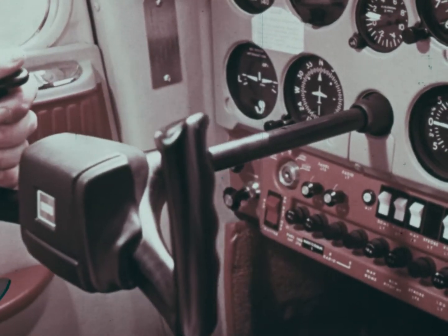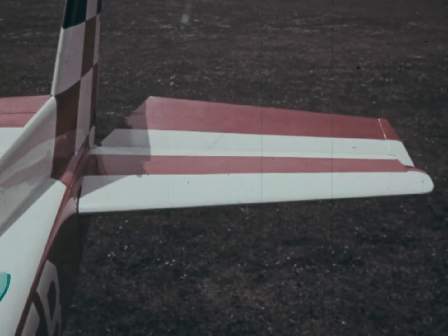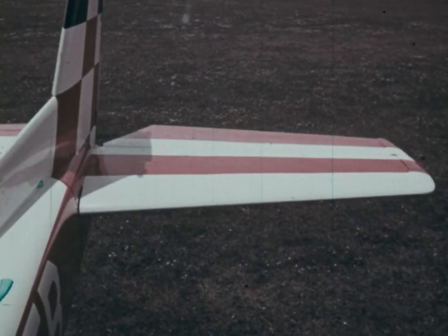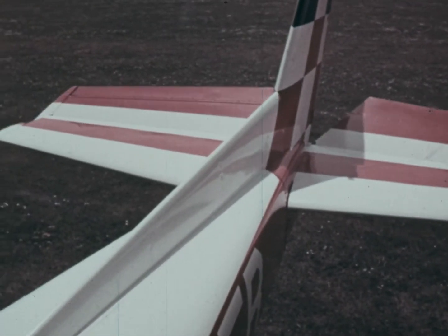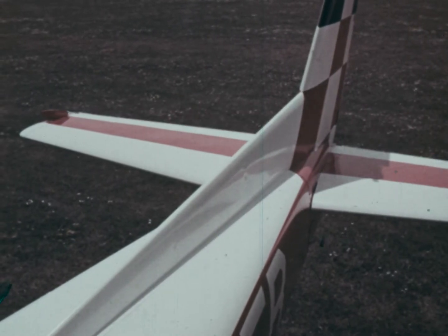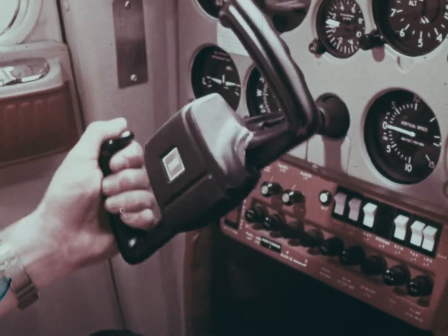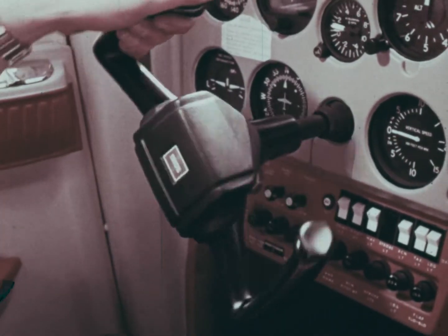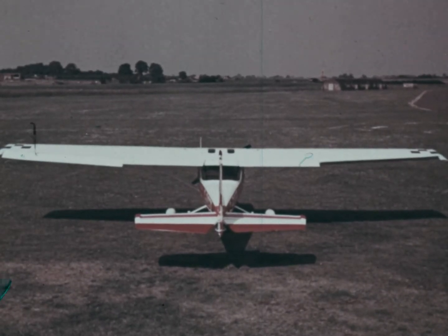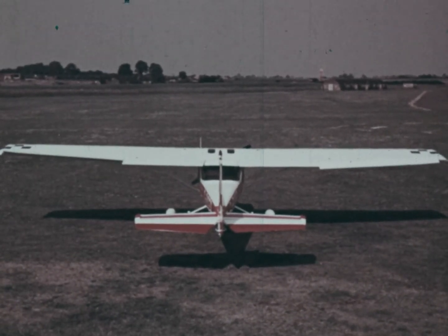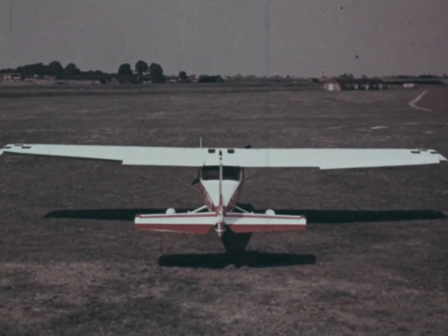Moving the control column backward and forward raises and lowers the elevator. Pulling it back raises the elevator. Pushing it forward lowers it. Turning the wheel operates the ailerons at the wingtips. With the wheel to the right, the right-hand aileron is raised and the one on the left is lowered, rolling the airplane to the right. Turning it in the opposite direction moves the ailerons in the opposite sense and rolls the airplane to the left.